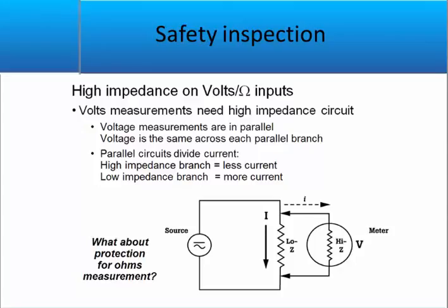It is possible that during the check the meter may fail due to a high voltage or out-of-spec voltage. So it's important to go through the three-step test: test on a known, test the unknown, and then test the known again.